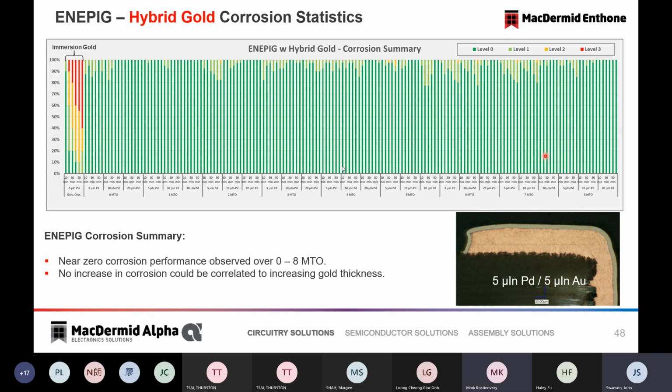Okay, and since you're dissolving nickel under palladium, that means you will have voids between palladium and the nickel. And third question is, when you solder to ENEPIG, obviously gold is dissolved, all right? So you are building only nickel tin intermetallics, or also palladium tin intermetallics? We find a bit of palladium in if you go thicker with the palladium.